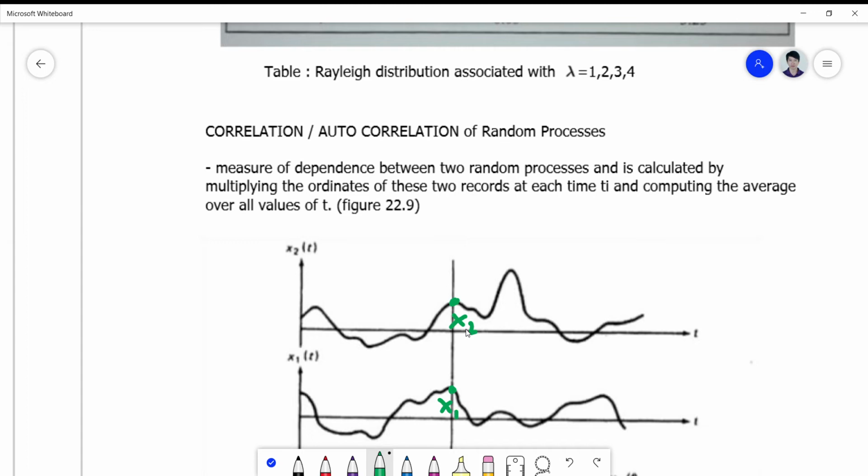Okay, so in this multiplication, what we do is we compute the average of this product over the time domain, which is from 0 to t. Okay, so we compute the average with respect to this time domain here. So if I have a lot of points on x here, okay, x there, I just take the average of this. I multiply x1, x2, x2, x3, x3, x4, and so on, or x1 of 1, x2 of 1, x1 of 2, x2 of 2, and so on. And then I take the average. I'm doing actually what you call a correlation. So that's the correlation process.